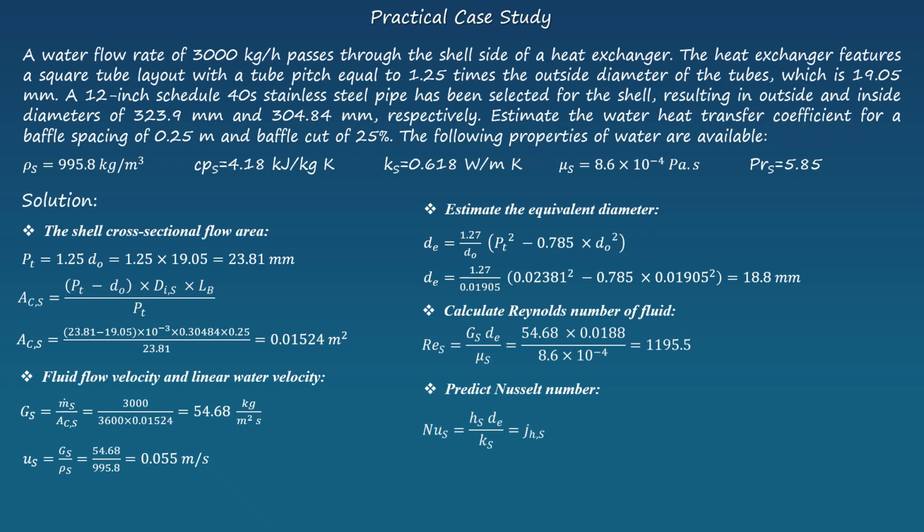If we use this value with the aid of the chart to get the Nusselt number, of course, we will neglect the last term of the Nusselt equation to neglect the effect of viscosity change with temperature, and then we will go to the final form of this equation as Nusselt number equal to a heat transfer factor times Reynolds times Prandtl to power 1/3.